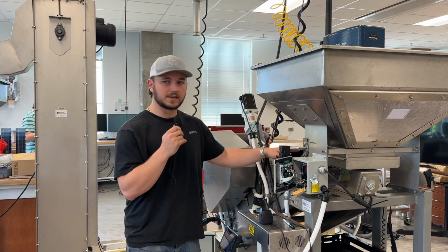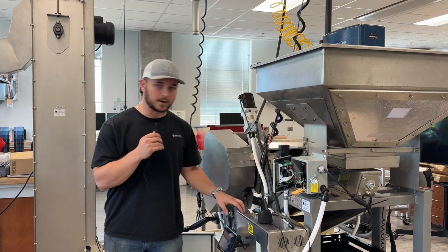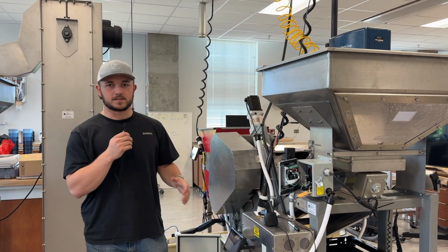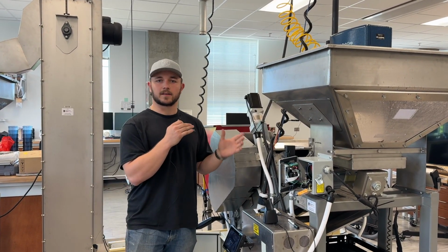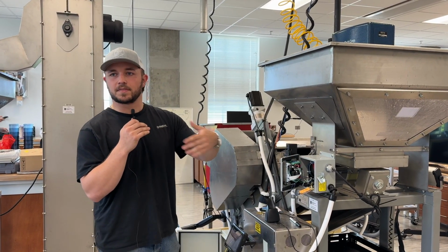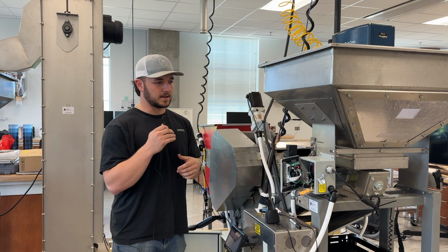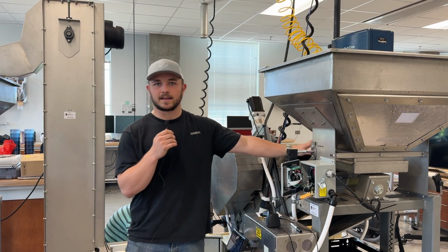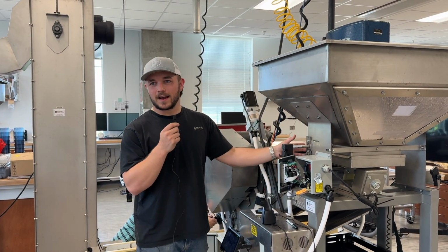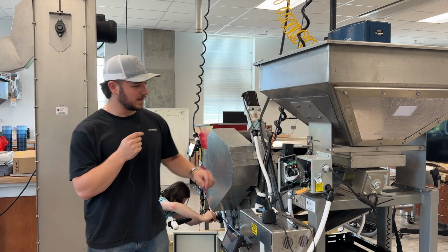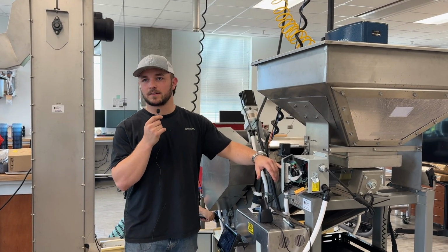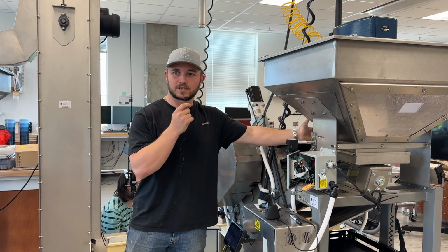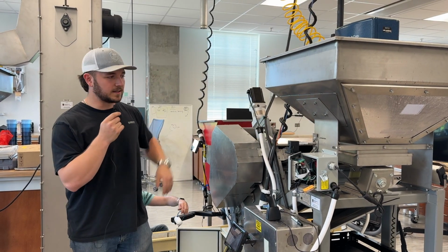One of those machine parameters that we're focusing on, our independent variable, which we're going to change throughout our experiment, is throughput. Throughput is a number that we back calculated from industry. We looked and saw what they were putting through their machines, and then we calculated 75 and 50% of that rate. And our goal was to replicate that here on our machine. Basically, we want to recreate the throughputs we're seeing in industry, and that involves changing the power unit here on this control box so that we're seeing the same, originally it was pounds per second of pecans coming through this conveyor as they do at the processor.